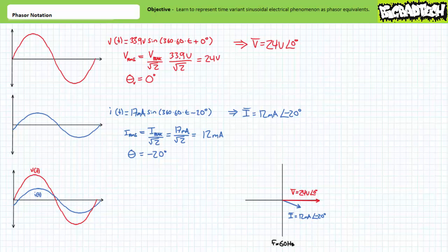As I previously mentioned, the origin of a sine wave itself is rooted in circular rotation and can be visualized as the height of a point traveling a circular perimeter of a given radius above or below the horizontal axis. The phase shift determines the angular amount by which this analysis is shifted. If we were to multiply the effective values by square root 2 and then rotate the voltage and current phasors on our phasor diagram in the counterclockwise direction, voltage would describe a sinusoidal path with no phase shift, and current would describe a sinusoidal path with a negative 20-degree phase shift, meaning it lags voltage by 20 degrees.